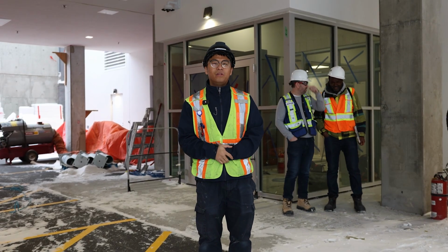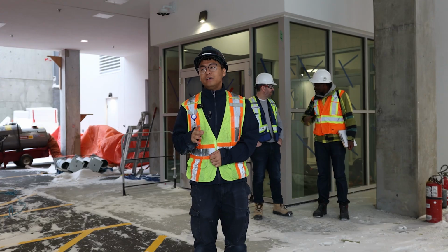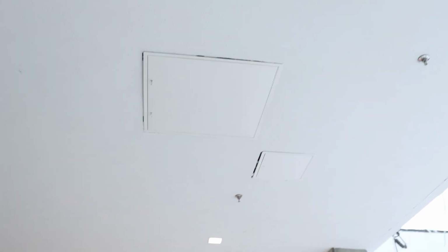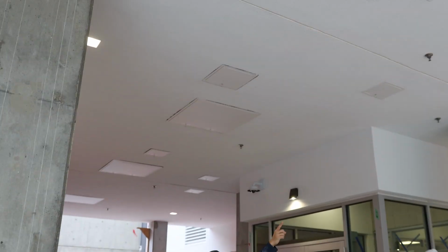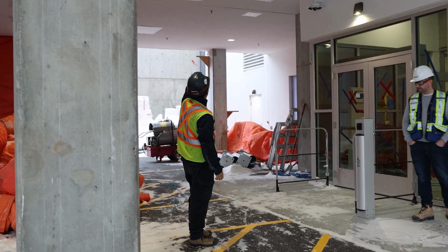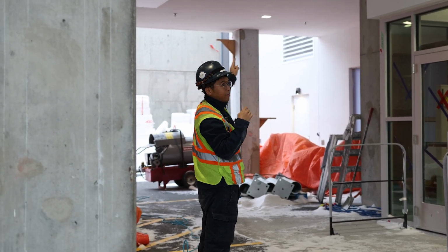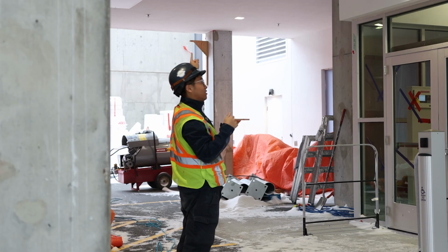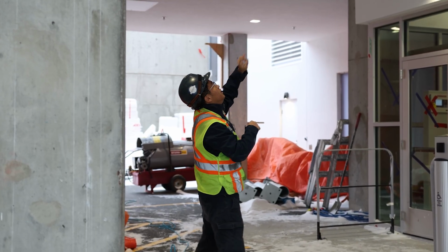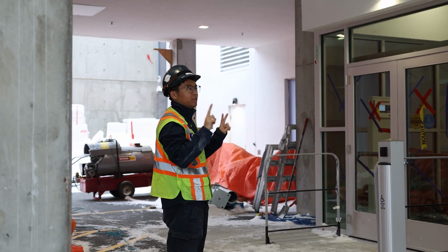Welcome to the parkade. The BMS controls the 4 electric makeup units for the soffit area. They will be behind those 4 big access doors, 1, 2, 3, 4. I believe the numbers will be EMA 1, 2, 3, 4. And we have space temperature sensors in the soffit area. EMA 1 and 2 share one space temperature, EMA 3 and 4 share one space temperature. So 4 units, 2 space temperatures.